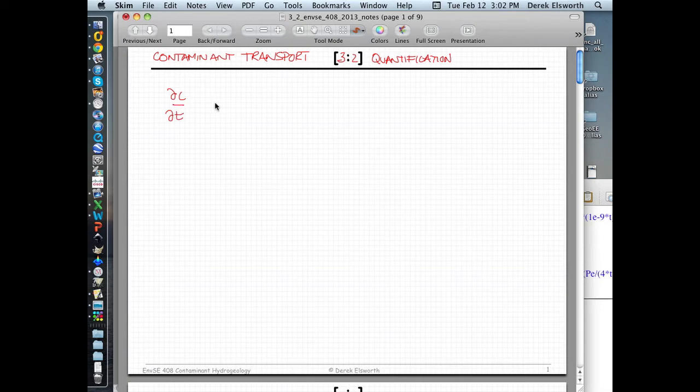So you remember, if you look at this 1D expression, it looks something like this. An accumulation term, a dispersion term, which says something about how stuff gets spread out due to mixing, mechanical dispersion, and also how it gets dragged downstream by an advective velocity in the x direction relative to a concentration being carried downstream.